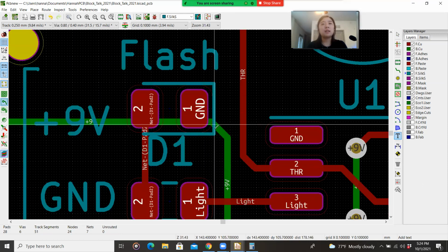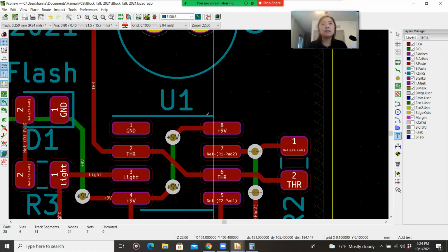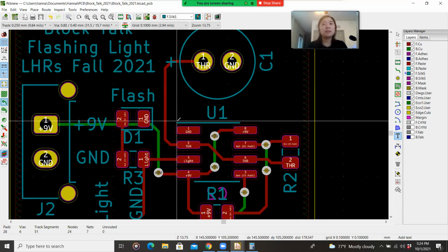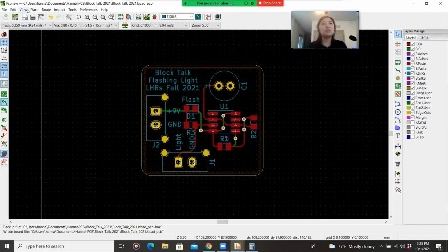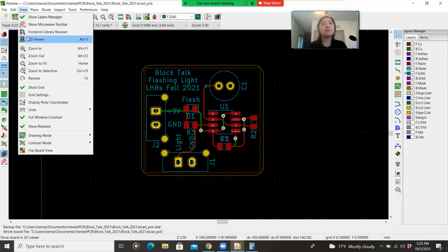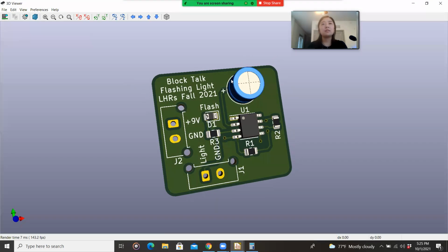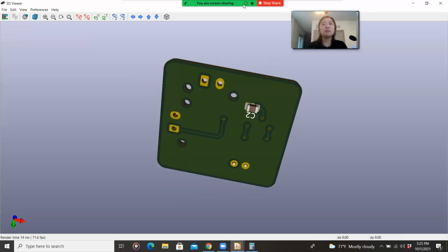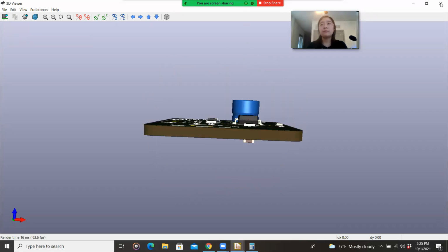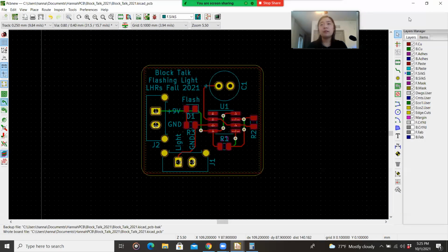Here, the diode footprint symbol already shows what side is ground. And here the chip already shows what side is pin 1 because it has that line over it, while the other sides don't. So you'll see there are certain unique indicators like that. Notice that you see a plus there, and you see these in the labels, and let's say we're fairly happy with this now.